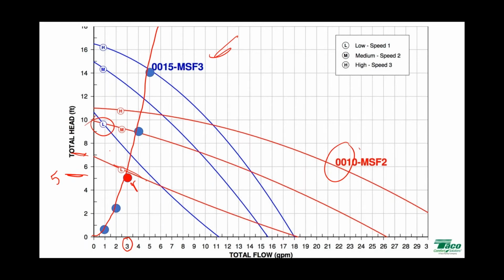They're almost always set to contractor no-callback mode, which, if you're a fan of the movie Spaceballs, is ludicrous speed. Because if a little is good, a lot is better, and if a lot is better, everything the thing can do has got to be the best, right? And we're talking about a good size zone here too. 30,000 BTUs is a big honking zone, and it was 163 feet long. That's a long zone.